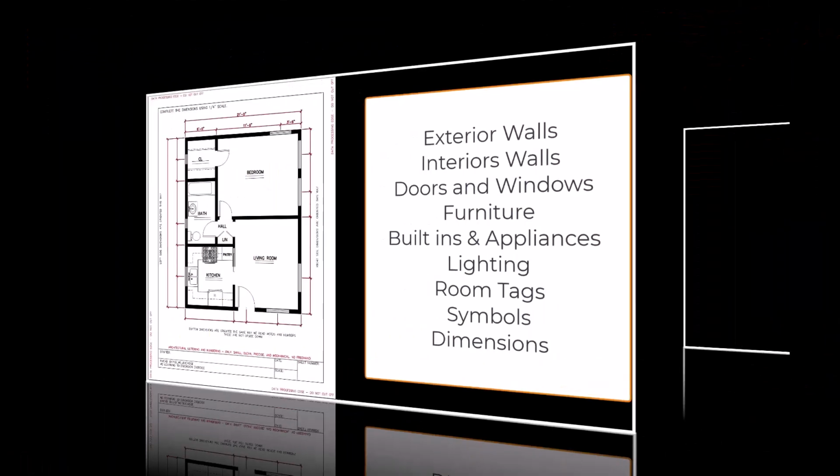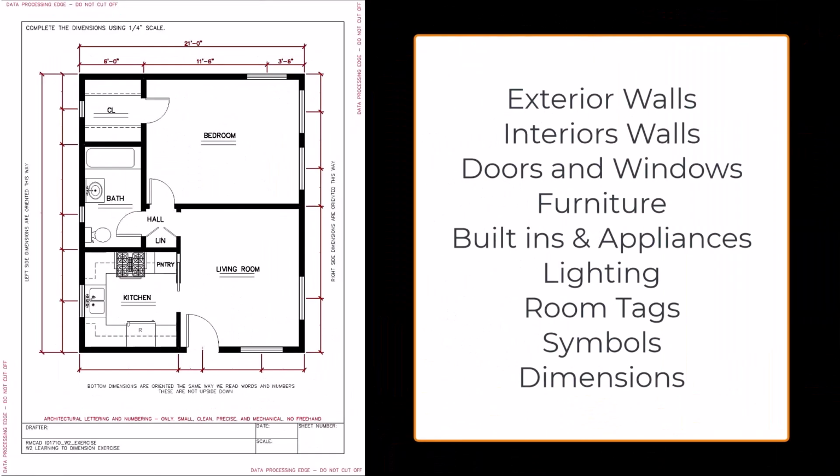And as you can see here in this example drawing, because it is printed out, it loses a lot of the nuances between all those different pencil line weights. If you're copying, especially as a student, we're turning them in virtually to our instructors. And in a 0.3, that fine window glass might not show up once you have taken a picture of it and put it in a PDF. And so we want to then make sure that after we've done that we're looking at it again and making sure that those line types are still showing up the way that they're supposed to.